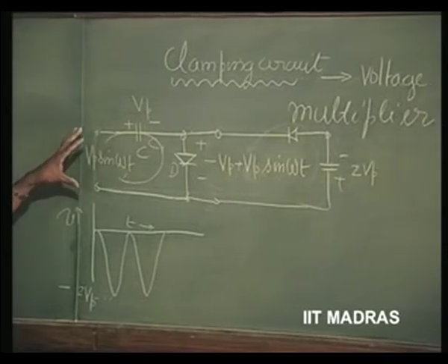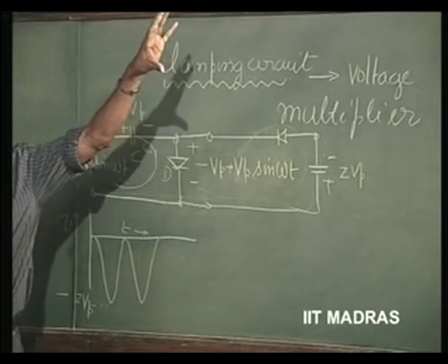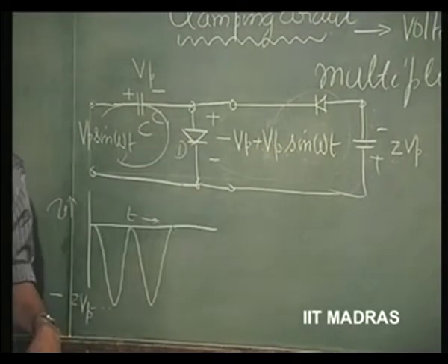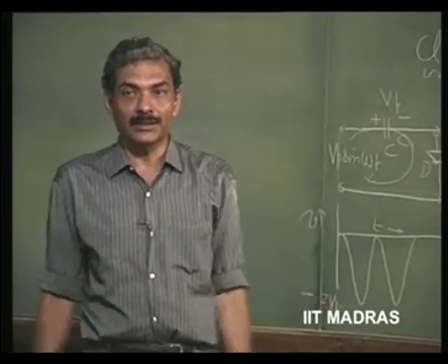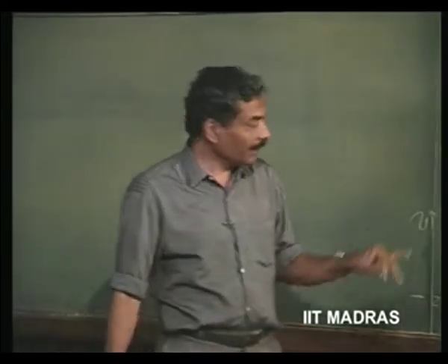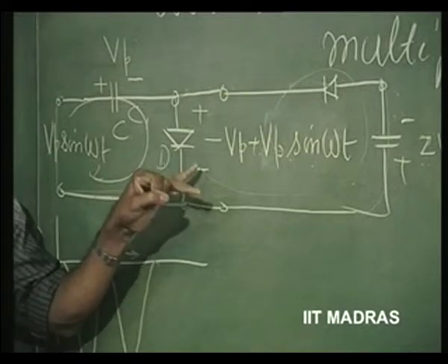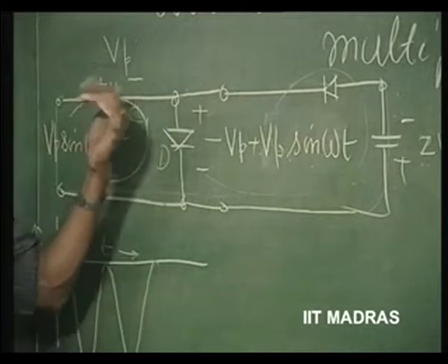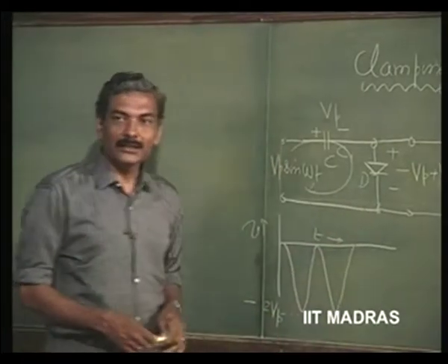So from a power line frequency, for example, 220 root 2 sin omega t, you can get very high DC voltages generated using this circuit. If the capacitors are good quality capacitors which have very low leakage, this is one of the simplest ways of generating high voltage DC without using any extra circuitry. This does not use a transformer, this simply uses only capacitors and good diodes which have good reverse bias voltage. They should not break down when such large voltages come across it. So if you use such good quality capacitors, they can sustain a large voltage as the DC voltage.